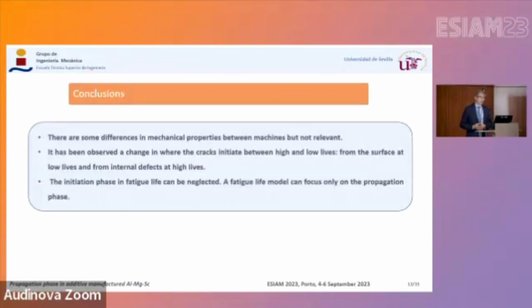So my conclusions were that there are some differences in mechanical properties between machines, but not relevant. It has been observed a change in where the crack initiates between low cycle fatigue and high cycle fatigue. And we think that the initiation phase can be neglected when we estimate the fatigue life.